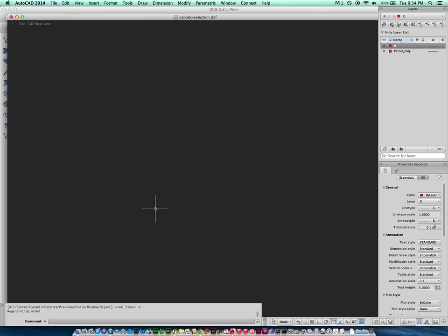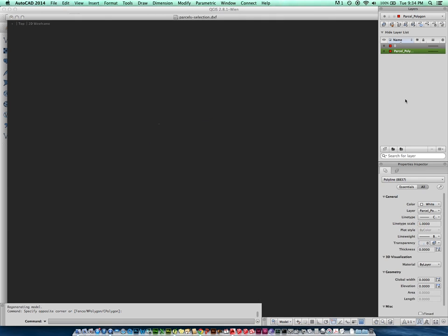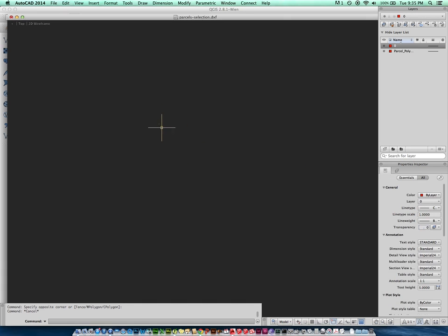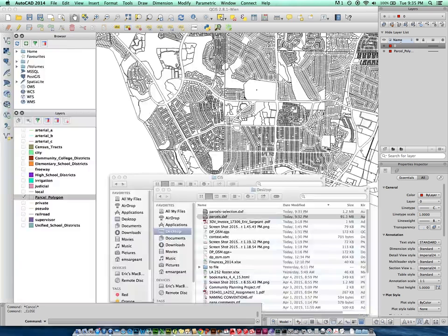What I have here is a scale issue. This is an issue that I've encountered. If I select this little white dot, it'll actually tell me that I have 8,833 polylines, but I can't actually get in to zoom it. Now there's a scale bust going on, even though the scale shouldn't be relevant for my export. So in this case, even though it shows there's information there, it's not accessible. I can't zoom window it, and I can't zoom extent it, nor can I copy and paste it in a new drawing. So unfortunately, even though it shows there's data there, I can't do anything with it.